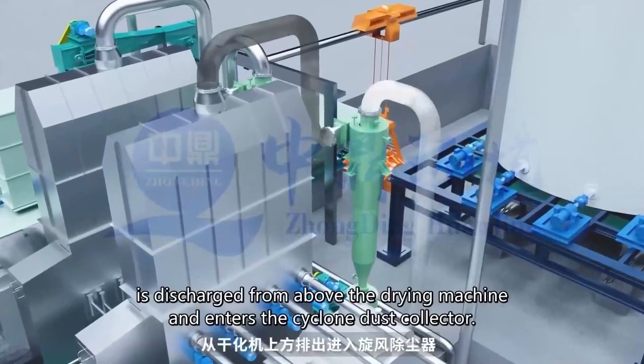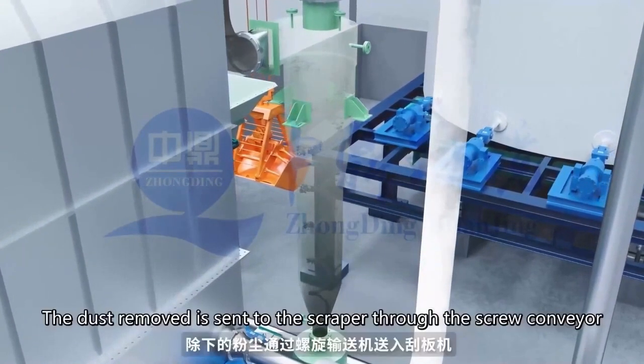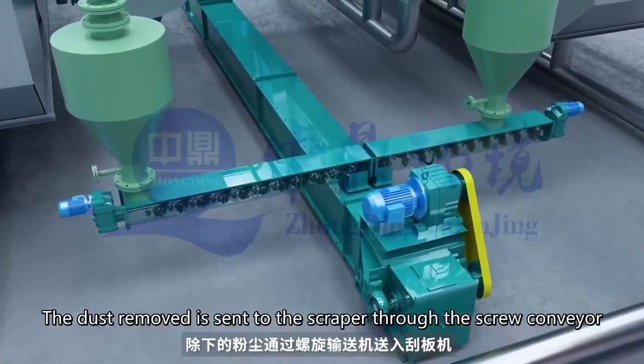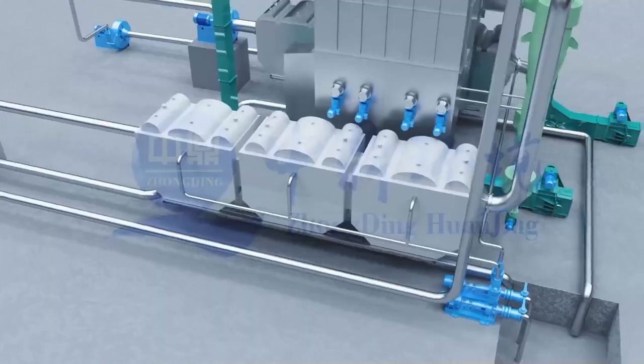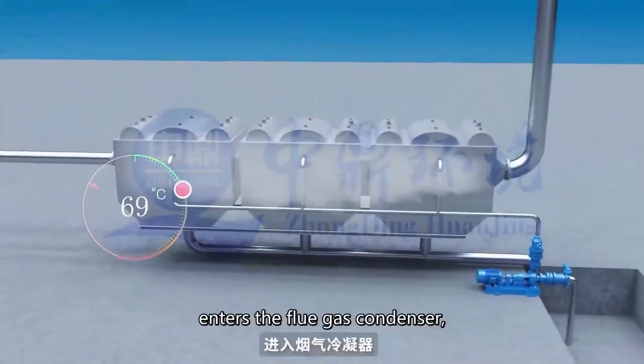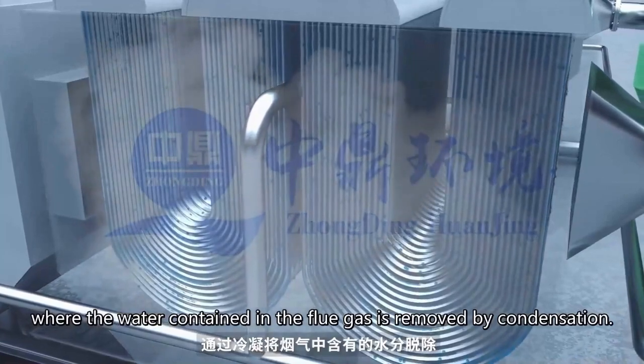The reheated flue gas is discharged from the top of the drying machine into the cyclone dust collector. The dust removed is sent to the scraper conveyor through a spiral conveyor, along with the dried sludge, and then sent to the incinerator for burning. The wet flue gas after dedusting enters the flue gas condenser. The moisture in the flue gas is removed through condensation.